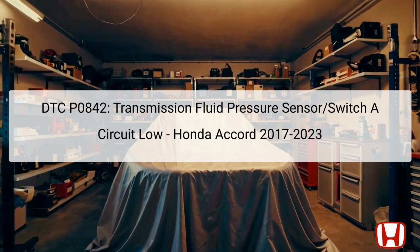The Diagnostic Trouble Code, DTC P0842, indicates an issue with the transmission fluid pressure sensor or switch circuit in the Honda Accord, model years 2017 to 2023. This specific code highlights that the circuit is reading low voltage levels, potentially leading to insufficient data being transmitted to the Transmission Control Module, TCM.